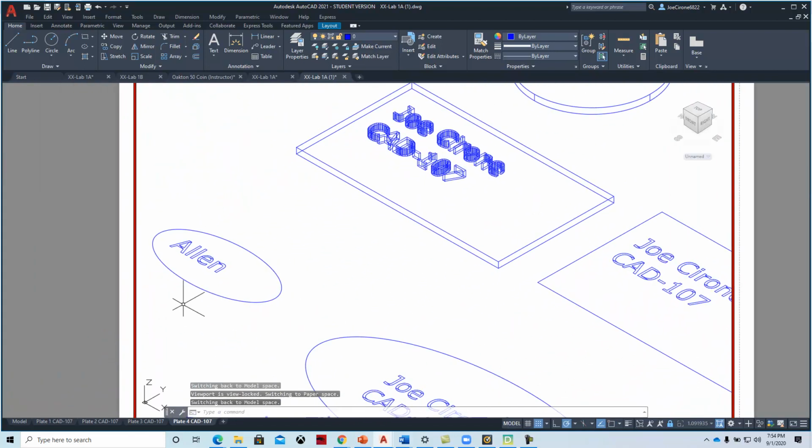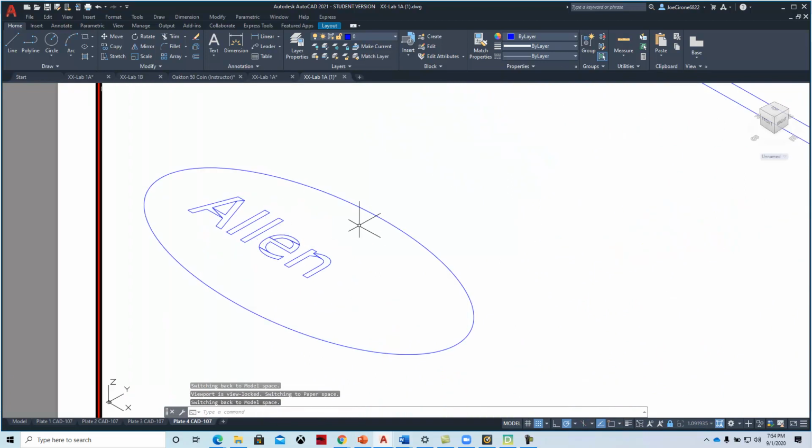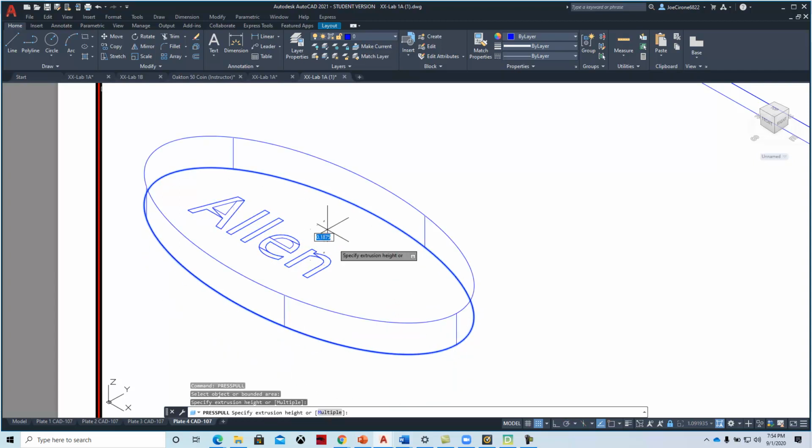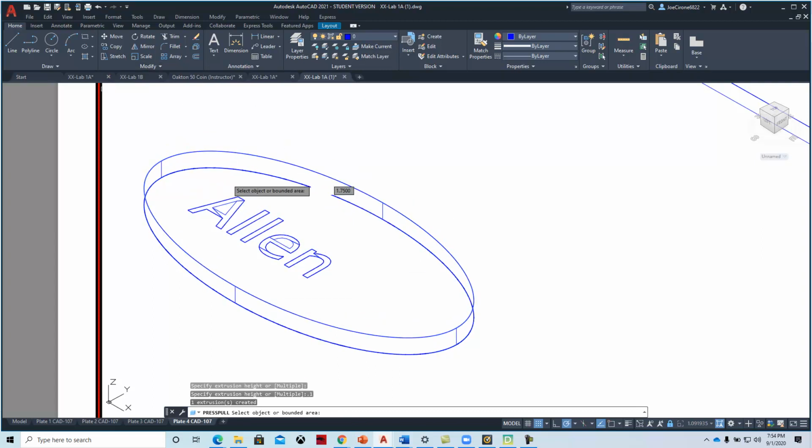And one more time for this tag. On this tag, I'm going to use press pull, and what it should do is create a negative shape of the letters. And so, and I think I should have spelled it AN, but so we'll say press pull, and then we'll click in this boundary shape. Now, what you want to do is get it so that everything highlights right there. Click, and then pull it up. We'll say 0.1, enter. And then let's take a visual style of that.